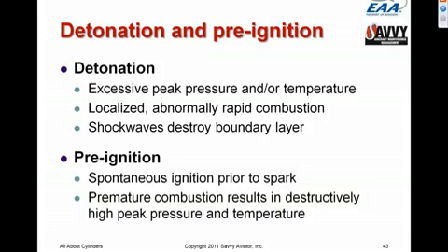So one thing that can cause detonation is substandard fuel that doesn't have full octane rating, but there are other things that can cause it. Advanced ignition timing can cause a detonation. Very high cylinder head temperatures can cause detonation.